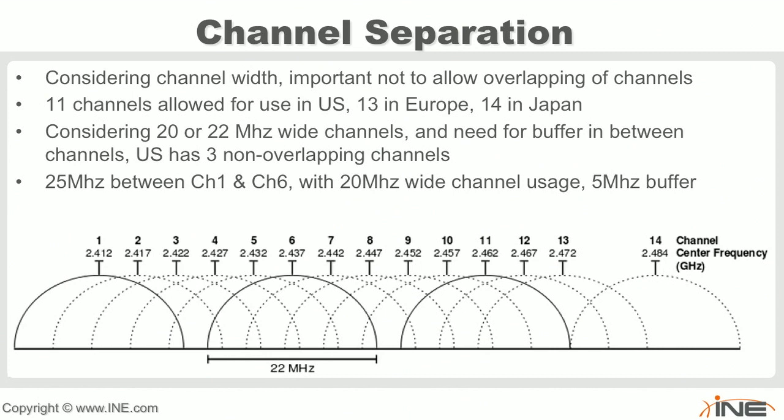And because we have to listen, if anyone is sending on a frequency that we are transmitting on, even on these peripheral frequencies out here at the edge, okay, not just in this center channel 6, but on any of the peripheral frequencies, we have to stop transmitting or not transmit to begin with, and we have to listen, and we have to wait till it's quiet.